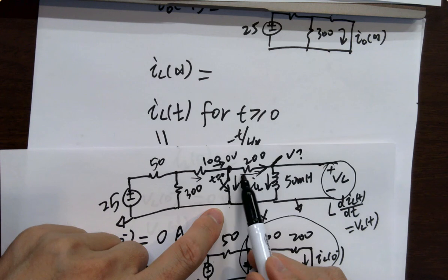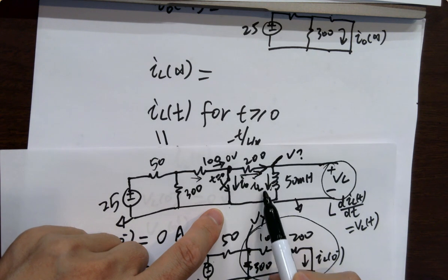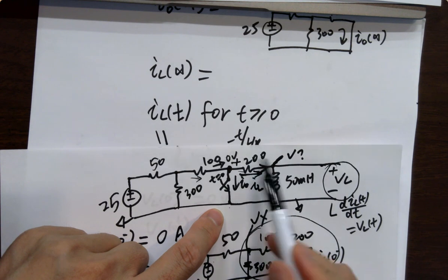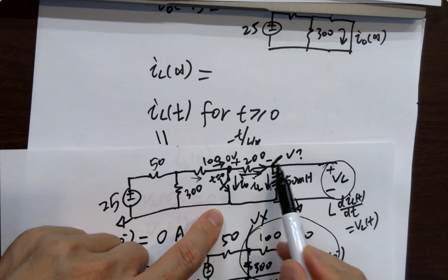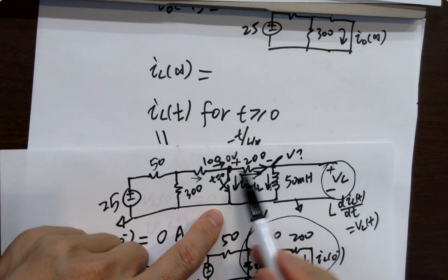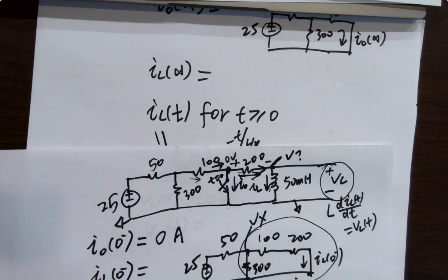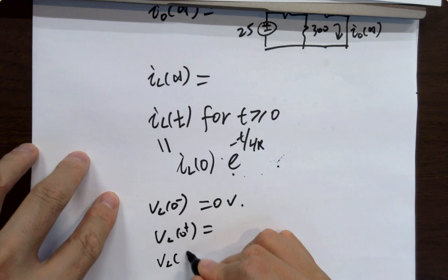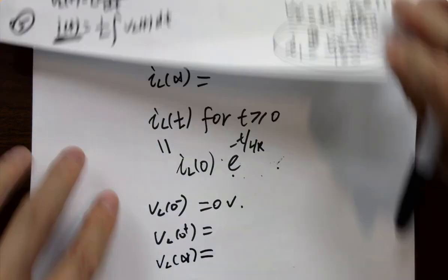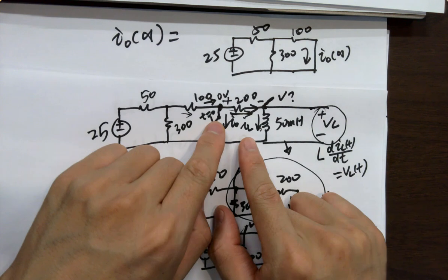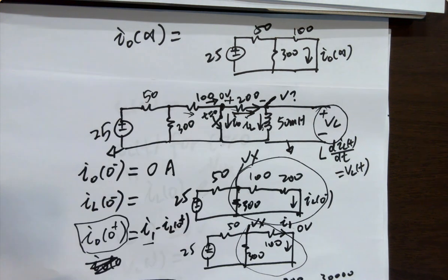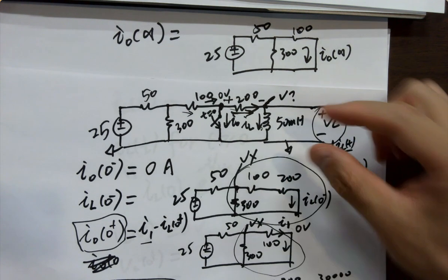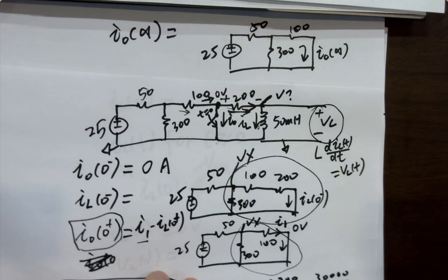Do you know the current at 0, the IL0? Yes, we know the IL0, the initial current. Boom, drop. What's the voltage here though? It's the negative of that drop. Okay? What about VL infinity? Close it. VL infinity. Natural response. Nothing left. 0.